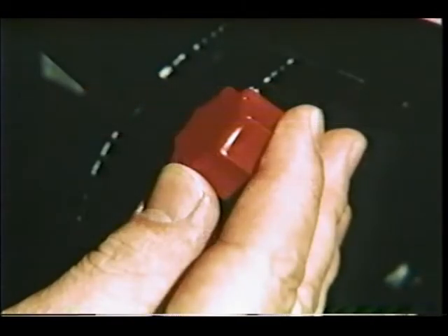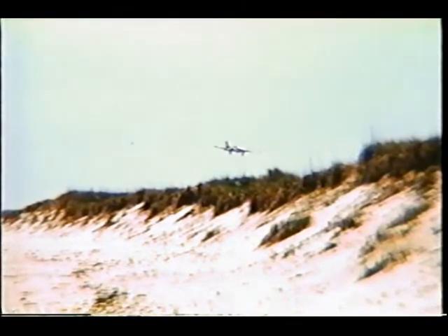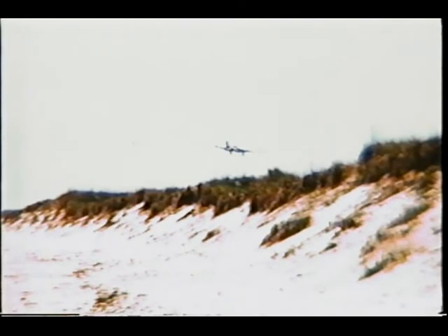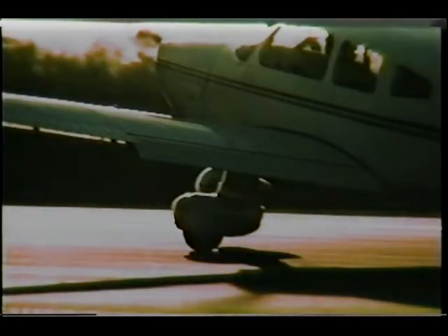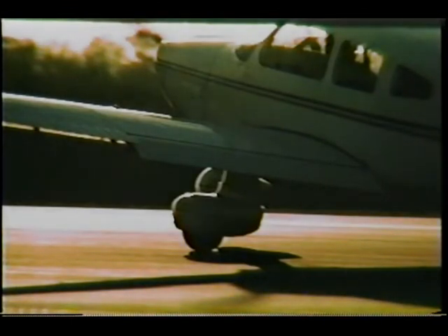High, hot, and humid also means there may be a potential need to lean the fuel-air mixture on landing to assure good engine performance, both on the approach as well as during the go-around. On the other hand, when elevation, temperature, and humidity result in a low-density altitude, a rich mixture will give you the best engine performance. Check your POH for specifics on performance, but figure on adding about 5% to the landing roll for each additional 1,000 feet of density altitude, all other factors being equal.